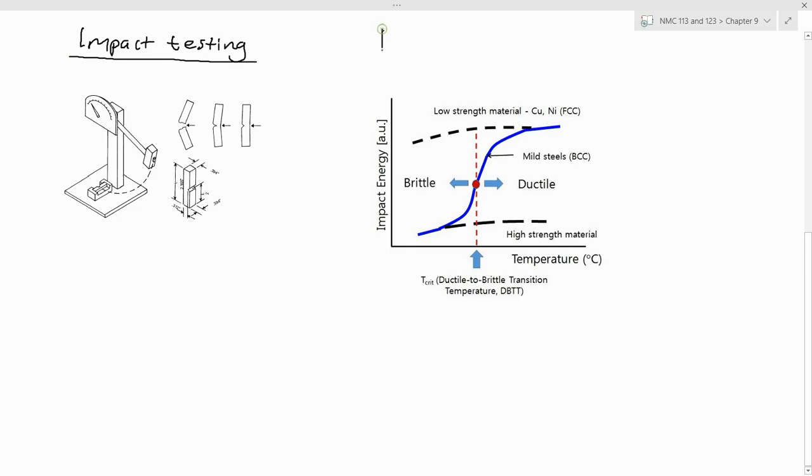If you look at the stress strain curve, this will be the stress, this is the strain. Let's choose a ductile type of profile. The area underneath this entire curve is actually the toughness of the material. Basically, how much energy is the material able to absorb before it fractures. Remember, this is different from the modulus of resilience, because the modulus of resilience is just the area under the elastic zone, but the entire area is used as a measure of the toughness.